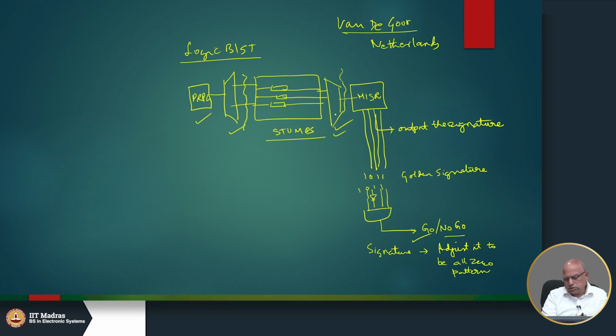But now it's all inside. Okay. So, some little extra area, etc., will be there. But more than that, what is unfortunately going to happen is we may not get adequate fault coverage. We may not get 100% fault coverage using only random vectors.